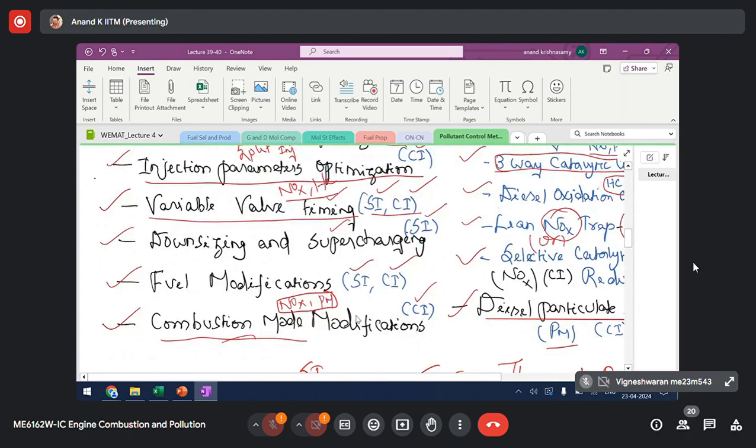So, Professor, sir, ideally variable valve timing or valve overlap is not recommended at low speed, right, sir? Low speed and low load. Low load is not desirable for a high overlap or retaining more exhaust gas, because that will have an effect on HC level. HC will be very high. So you have to have a closed loop sensor to monitor the pollutant level. If HC is very high, don't retain more exhaust in the cylinder. If NO is very high, retain more exhaust in the cylinder.